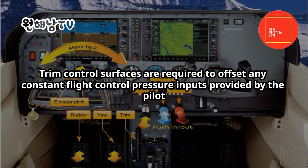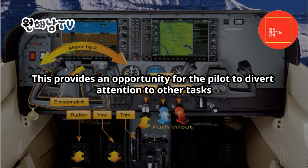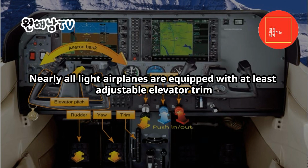Trim control. Trim control surfaces are required to offset any constant flight control pressure inputs provided by the pilot. For example, elevator trim is a typical trim in light GA airplanes and is used to null the pressure exerted by the pilot in order to maintain a particular pitch attitude. This provides an opportunity for the pilot to divert attention to other tasks. Because of their relatively low power, speed, and cost constraints, not all light airplanes have a complete set, elevator, rudder, and aileron, of trim controls that are adjustable from inside the flight deck. Nearly all light airplanes are equipped with at least adjustable elevator trim.